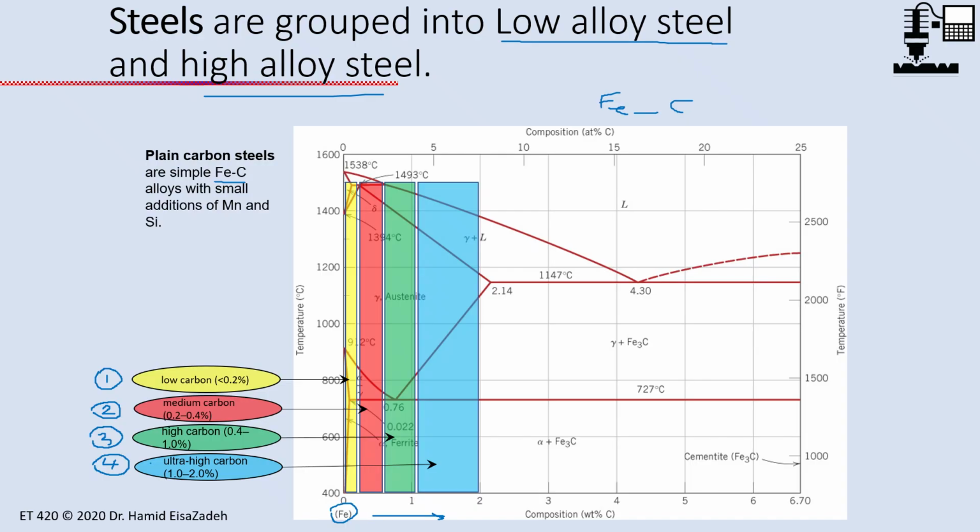In that steel, it's not heat treatable because the amount of carbon is low, and you cannot form martensite. If you want to form martensite, the amount of carbon should be at a certain level, so the carbon is going to be trapped in the austenite. Then you can form martensite. But here, because the amount of carbon is low, martensite formation is going to be very difficult.